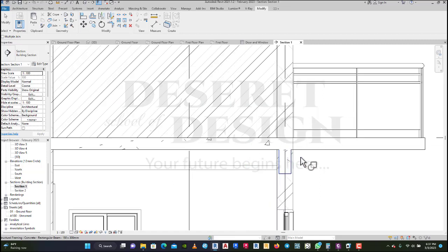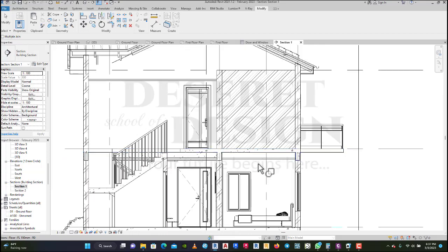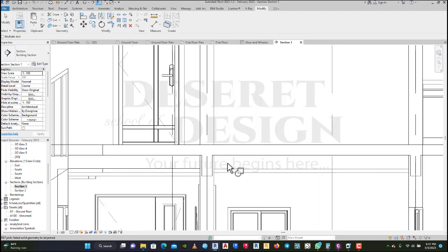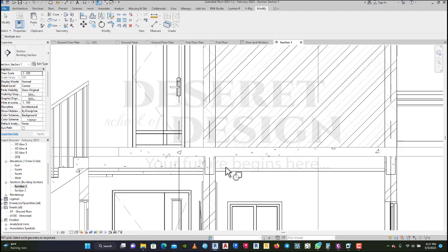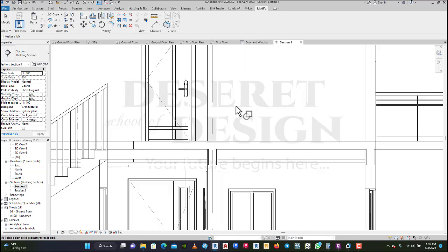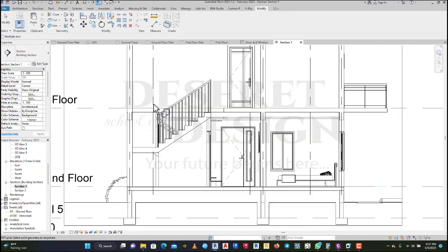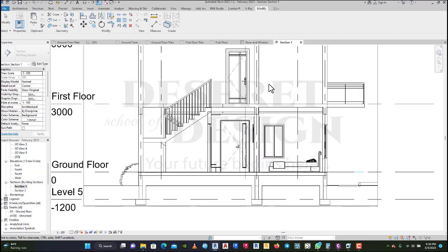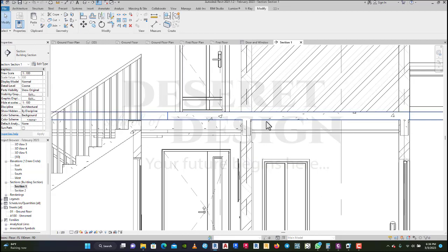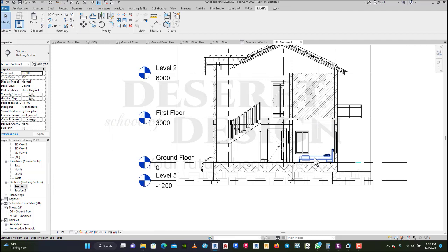And please, don't miss it. If you miss it, you will see that thing is not working. So I beg you. Either wall and beam should be the first thing, whichever one you choose, the wall or the beam. Then when you finish, either the beam or the floor. Do you get it? Okay, so that's the way you have to go. You do this to trim them nicely and let it look neat.